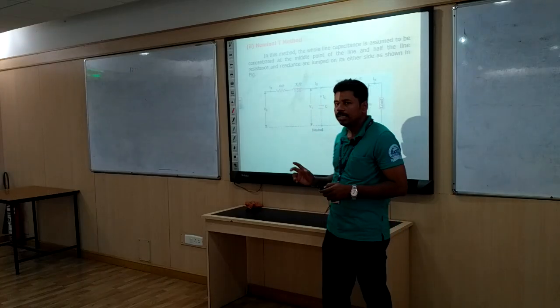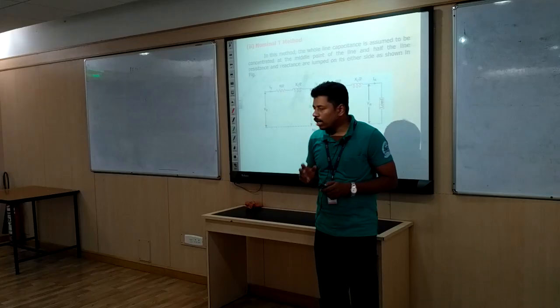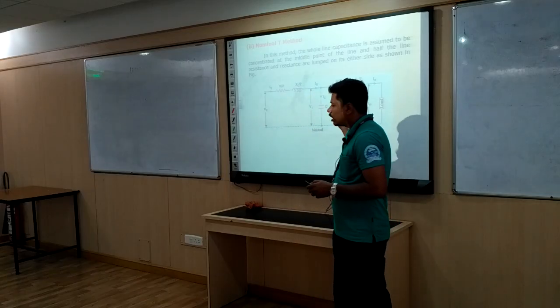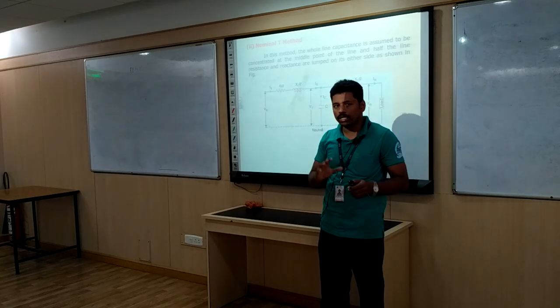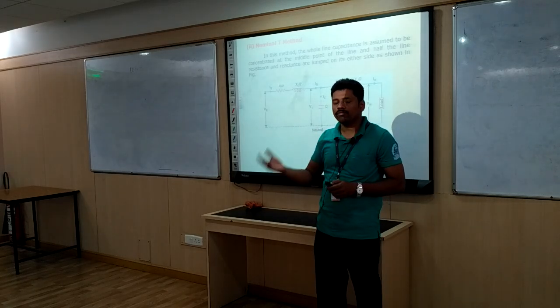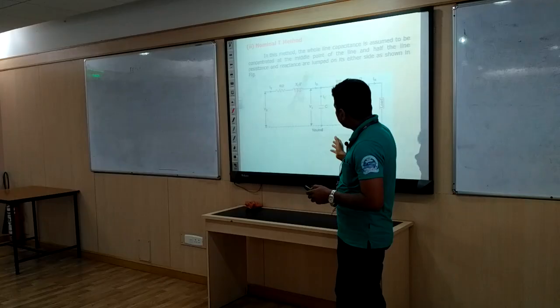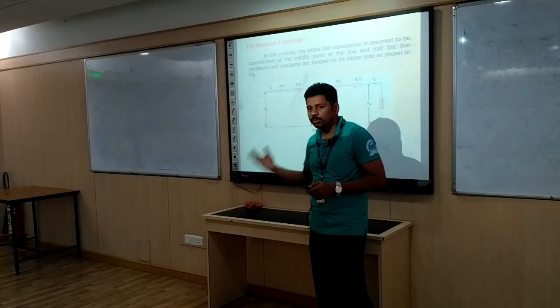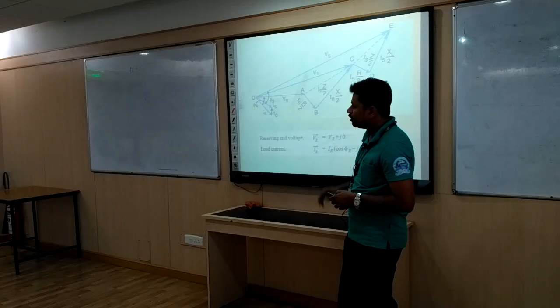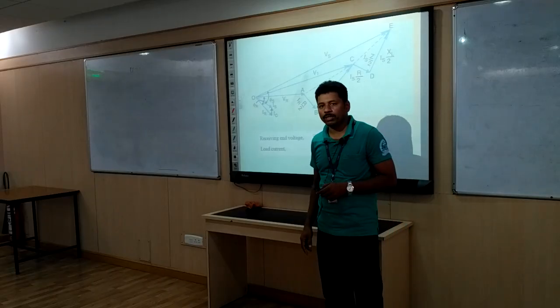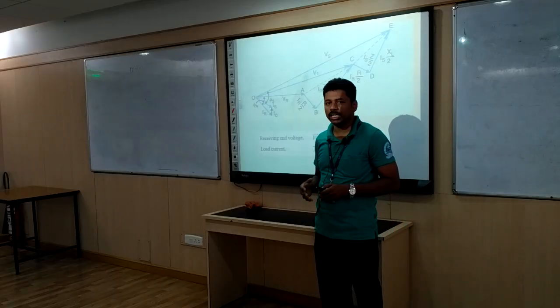For this we need to write the voltage and current relations. While writing that, first write V1 in terms of Vr. V1 is the mid voltage. Find V1 in terms of Vr, then find V1 in terms of Vs. And the current relation is, as in the previous case, Is is equal to IR plus IC1. This is the vector diagram or phasor diagram to represent all the relations between the sending end voltage, receiving end voltage, etc.